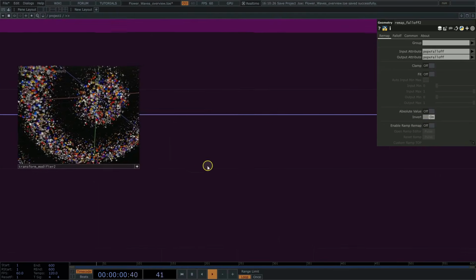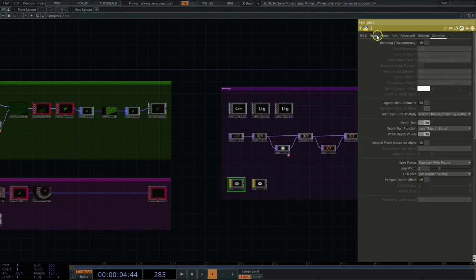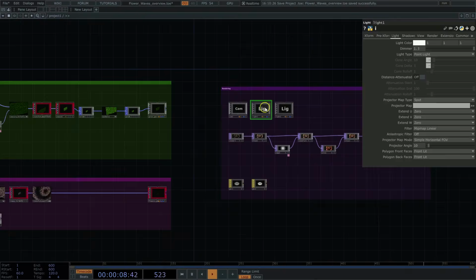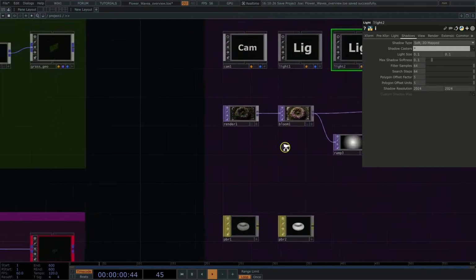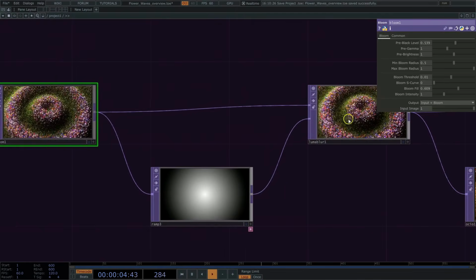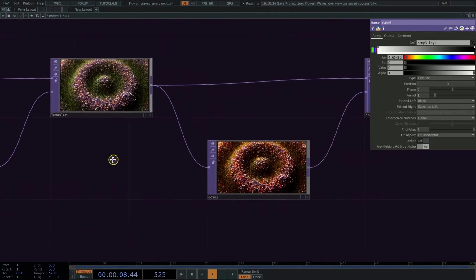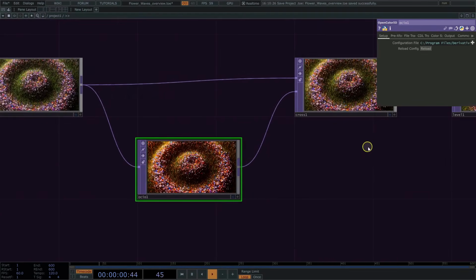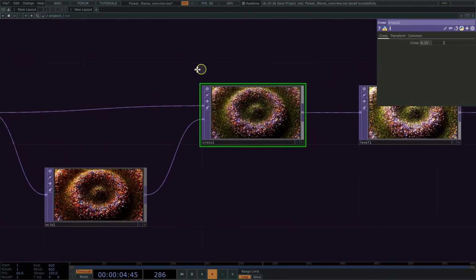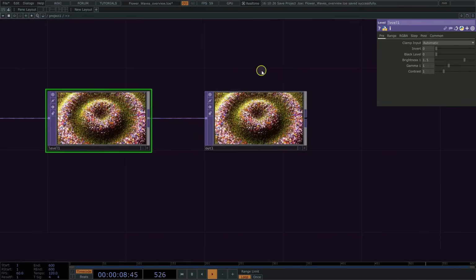And finally, rendering. PBR materials for the grass and flowers with a camera and 2 colored lights with soft shadows. A bloom top adds glow. A luma blur driven by a circular ramp top softens the edges. An open color IO top runs a color filter mixed back over the original with a cross top. A level top boosts the brightness for the final image. Alright, let's get started.